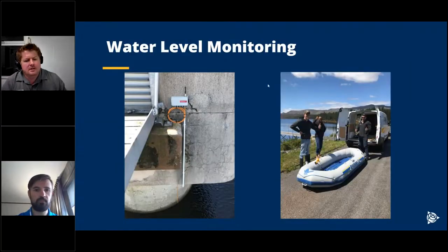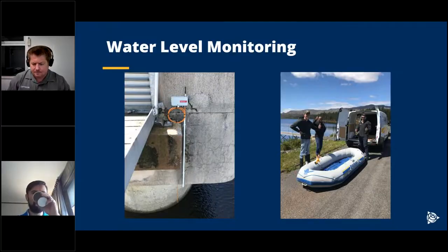So this is just the piezometer installation at the Steenbras upper dam wall. The upper dam wall is probably about 5 kilometers upstream from the lower dam. So this is where the load sensing devices come in very handy, because we only installed the piezometer. We don't need to install power or network over here. It's all taken care of by the wireless data logger.